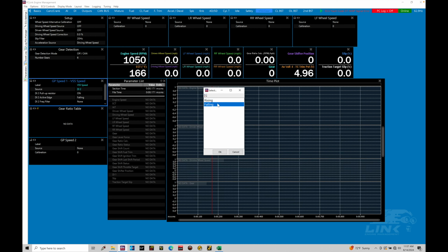If what we're looking for on a scope when we're looking at a VR sensor is where, looking at the waveform coming up and down, we have the fastest rise or fall in the signal, which will designate in that sinusoidal wave if it's rising or falling. We talked about how to determine that in the cam and crank tutorial, so you can go back and take a look at some more specifics with setting up a reluctor sensor.